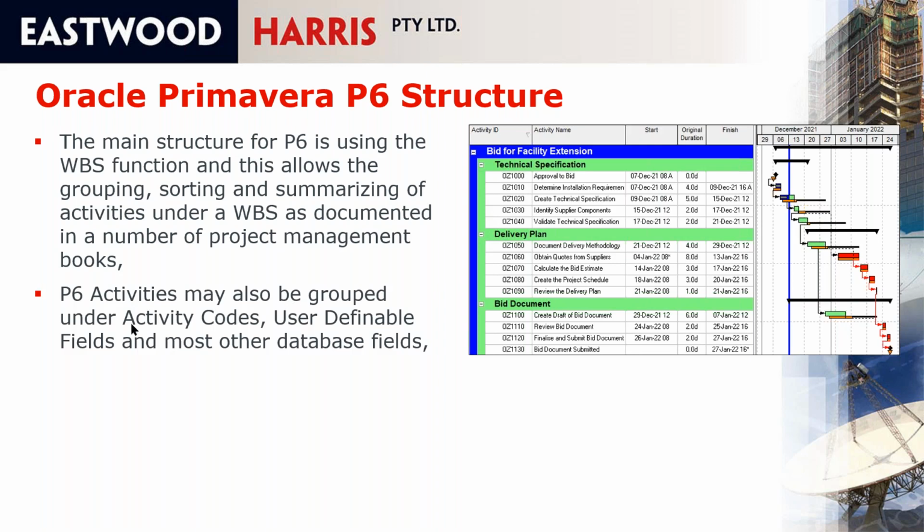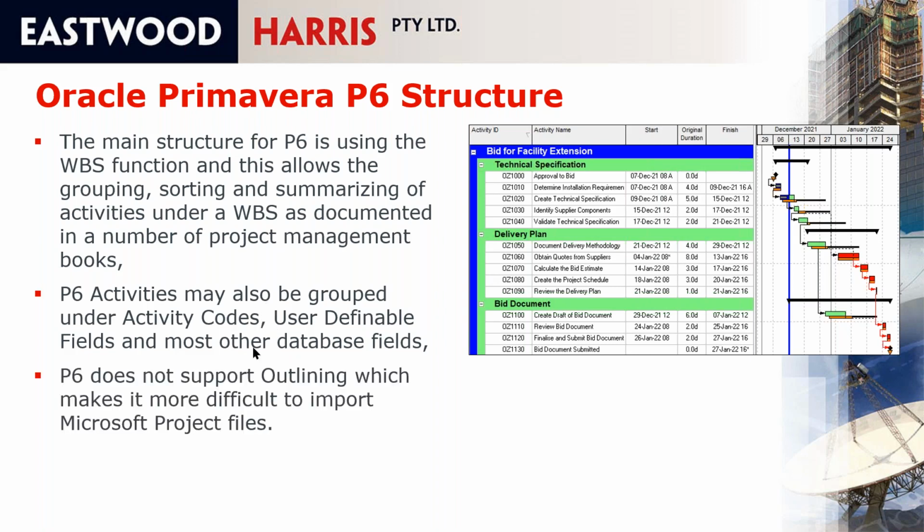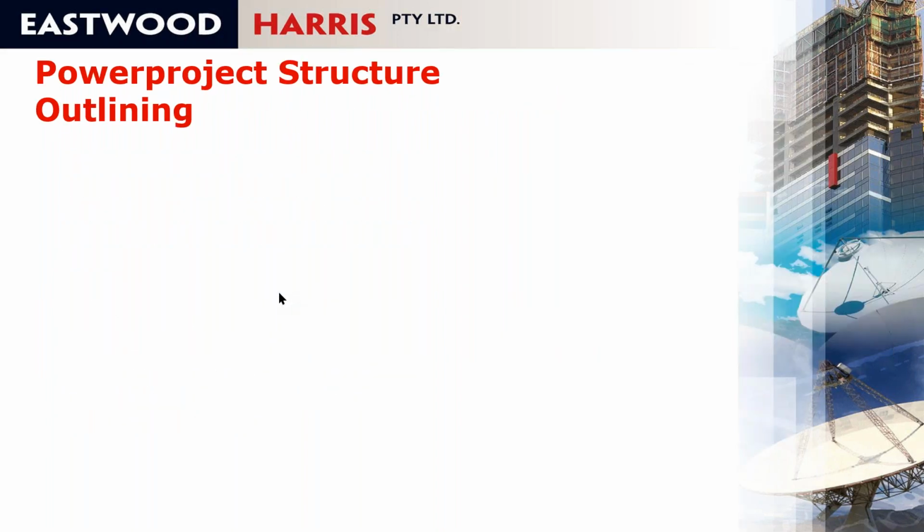P6 activities may also be grouped under activity codes and user-definable fields and most other database fields as well. It doesn't support outlining, which is where you have summary activities, which makes it a little more difficult to import activities from Microsoft Project. But the principal way of organizing activities is by a WBS and then also grouping and sorting under activity codes or user-definable fields.